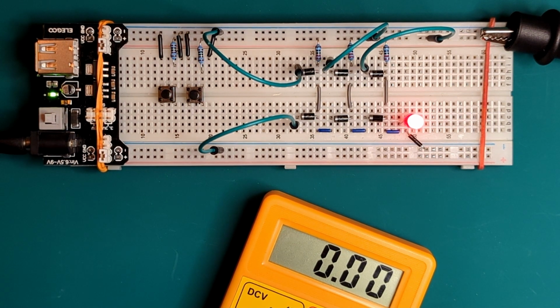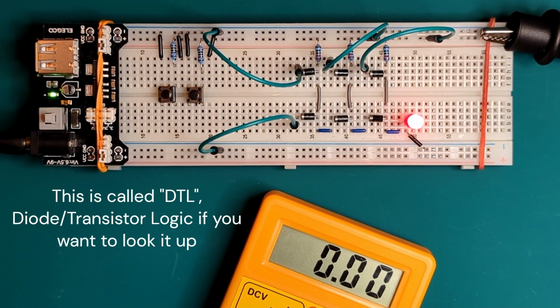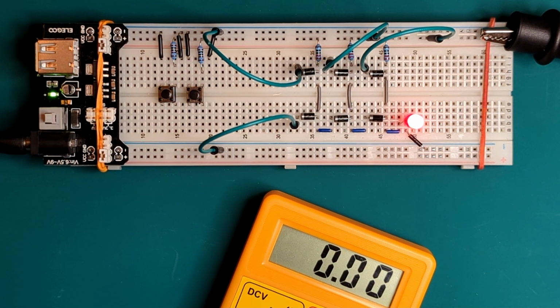There's no solution just with diodes to prevent this signal degradation. You could use other components like transistors to fix it, but we'll see soon that the components you'd use can be used to build gates on their own. So an error on the signal by itself wouldn't be a big deal, but the problem is that the errors are being compounded. That means that when we chain gates together, the errors will accumulate until we don't know what's a high or what's a low. So diode gates kind of work in some situations, but they have a rough time complying with rule number 1 and rule number 2 at the same time.